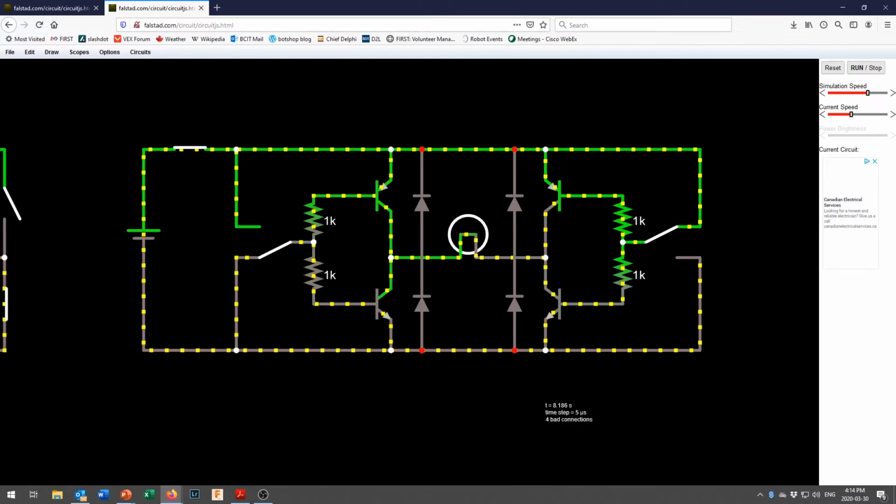We'll turn that back on. We'll get some electricity flowing through right there. You'll sometimes also see a switch called an enable switch. And the enable switch is basically a master on-off switch for your H-bridge. Before I started adding the diodes, I should have pointed out the reason it's called an H-bridge is you can see one leg of the H right there, the crossbar of the H right there, and another leg of the H coming down right in there. So it's called an H-bridge because it kind of looks like an H when you draw the schematic out.